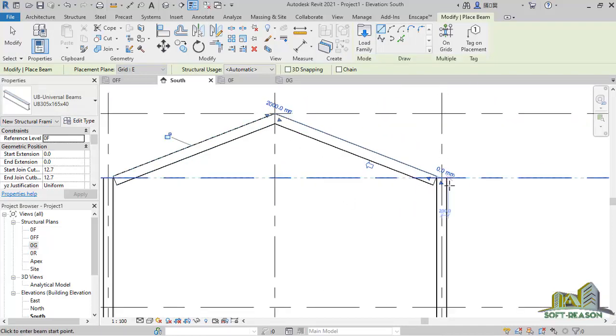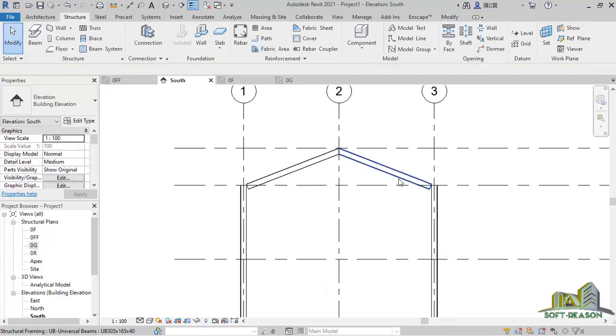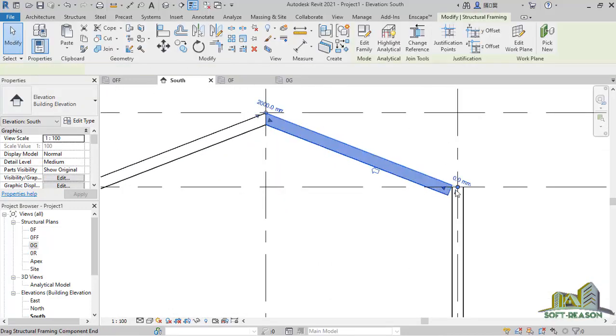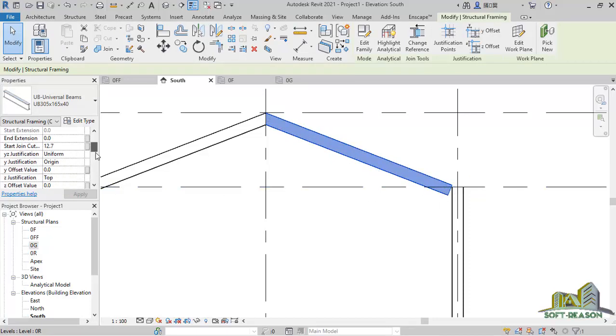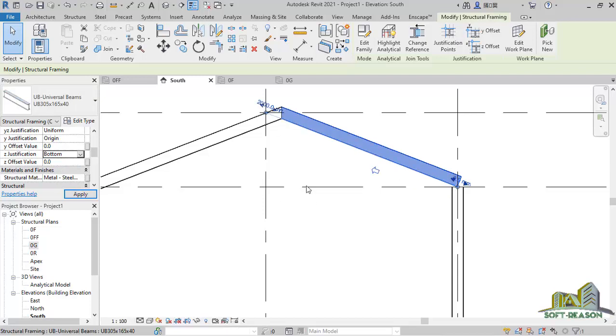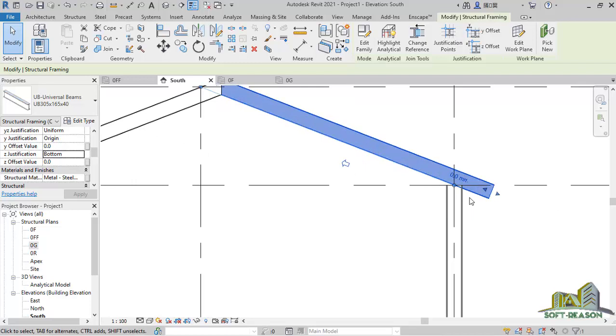Alright, to have my rafter just like this. Okay, and so I could be able to extend this rafter or set this rafter in such a way that, for instance, if I come to this justification and click on this point and then take the button, you will notice that this goes up. Alright, just like that. So by so doing, I can hold it there and then be able to extend it just like that. But if I do that during connection design, it will actually not work properly as I expected,